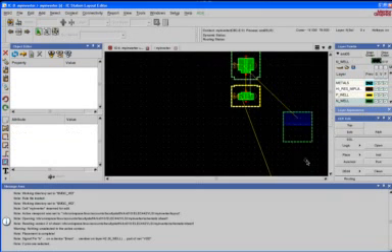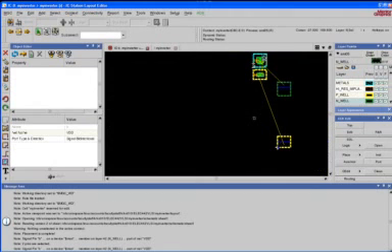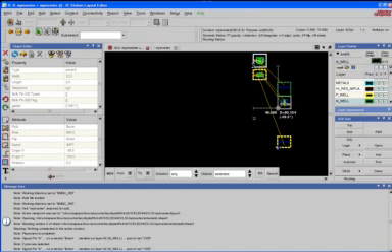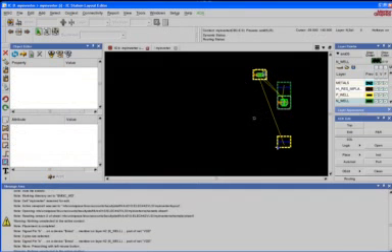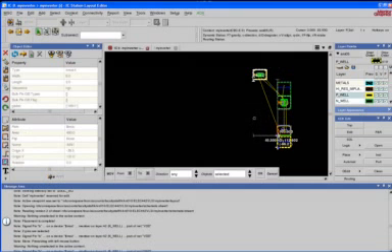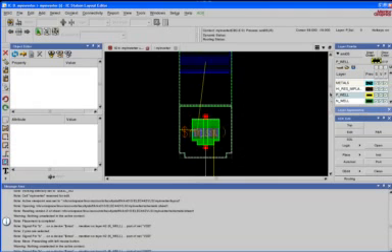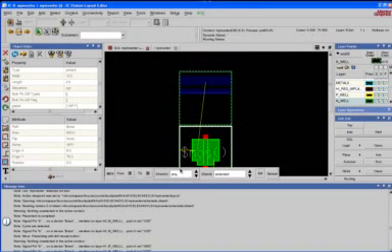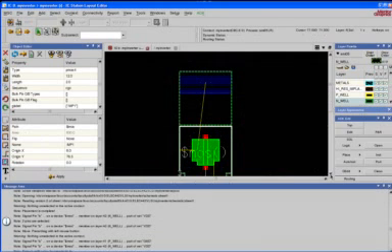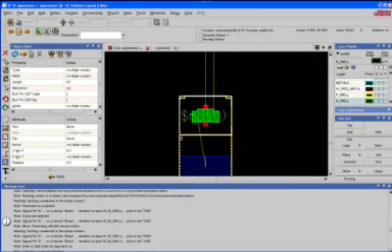Now let's zoom out a little bit. We're going to move the PMOS down here and the NMOS down here. Select the PMOS. Click on move, and place it down here. To unselect, press F2. Move and bring it down here. To unselect, press F2. Now let's zoom in on that area. When you place it, make sure it's overlapped a little bit with the green. And up here, let's move this so that these two overlap.